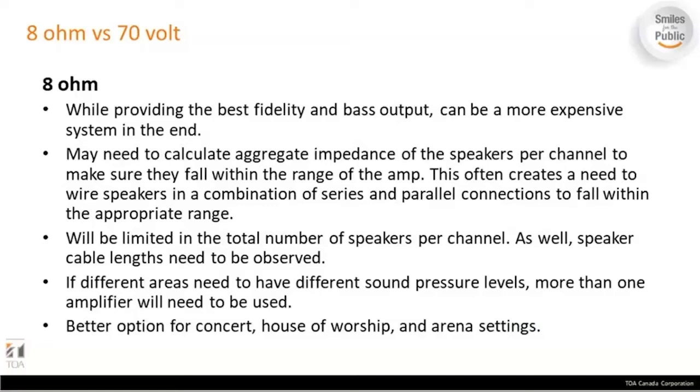So 8 ohm is considered to be low impedance, and the 70, actually this is 70.7 volts, not 70, 70.7 volts is considered to be high impedance. So where is the 8 ohm speaker used? Usually it is used where we need the best fidelity, where you need good bass, and budget is usually not a constraint, and you need a more expensive or high-end system, right?